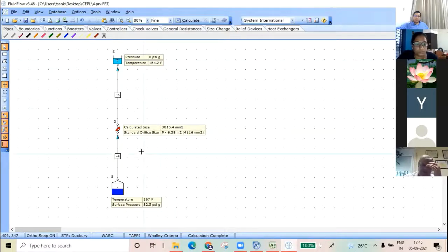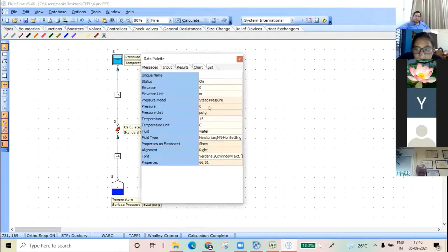So we can trust this temperature out. So this was example 1, right? This was for critical flow, if you remember. Now for subcritical flow, we had some other input for outlet, PSV outlet, which was 55 psig. Remember example 2, 55 psig. So please change that input for the tank PSV outlet from 0 psig to 55 psig. And again run it.